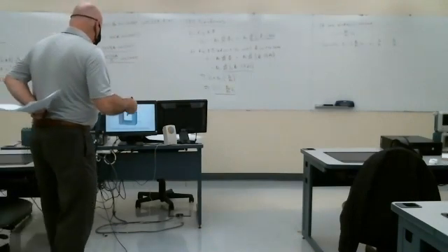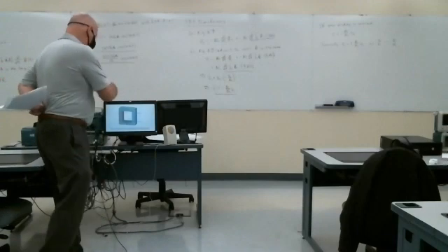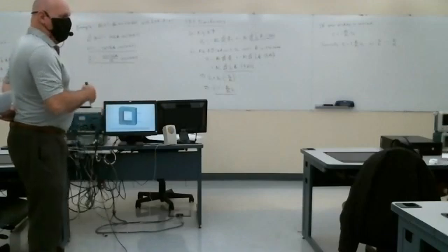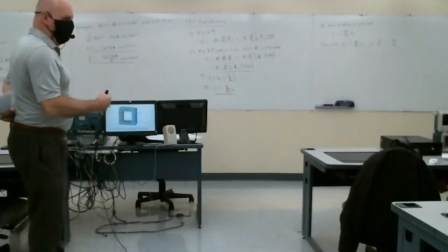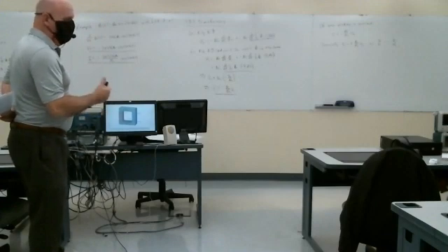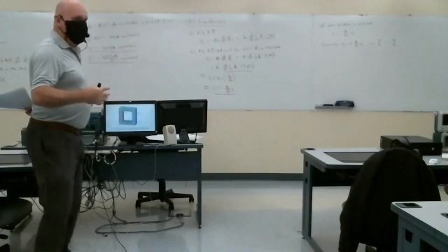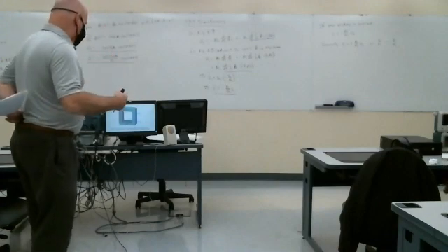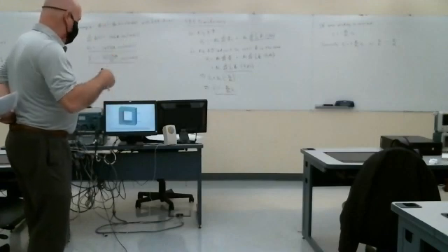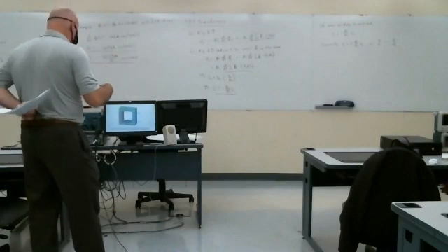The procedure is like this: if you start in the primary coil, you treat the primary coil as a load, so current is flowing into the plus terminal of the coil. Whereas in the secondary, you assume the current is flowing out of the plus terminal. It flows from the minus around through the coil out the plus terminal.